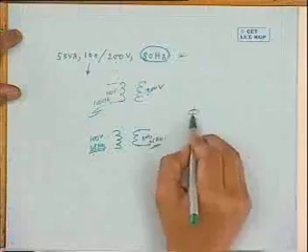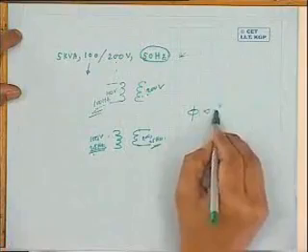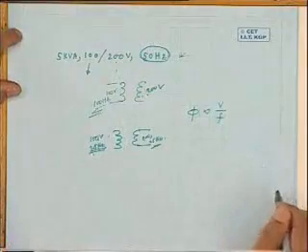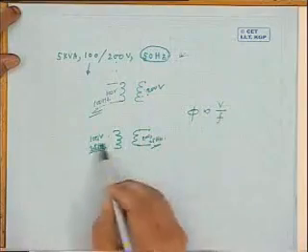Now if I apply 100 volt, 25 hertz, that flux level has to be how much? 4 times? Only 2 times. It will become double, because V by f decides the flux level. Flux level in the transformer is proportional to applied voltage divided by frequency.